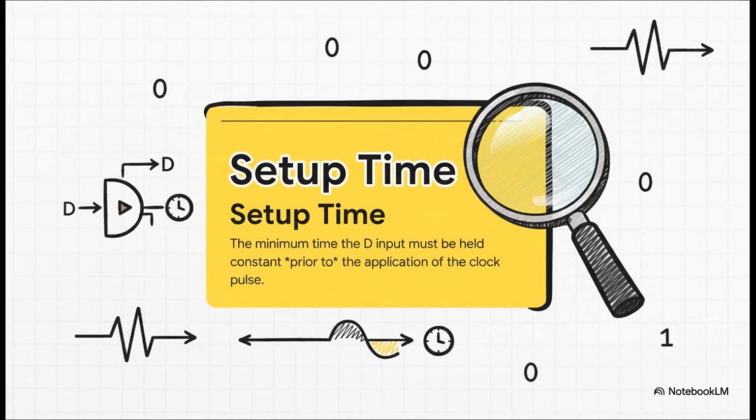Now, to make this work, there are a couple of very strict rules. The first is setup time. Think of it like taking a photo. The data you want to store has to be held perfectly still for a tiny moment before the shutter clicks, before that clock edge arrives. This gives the circuit a chance to get a clear look at the data.